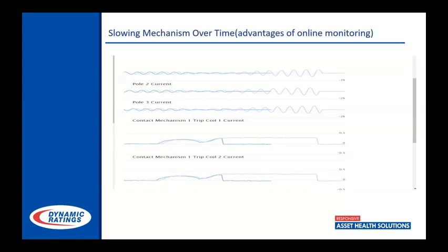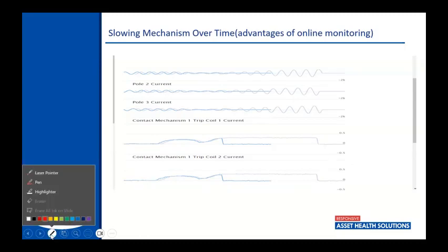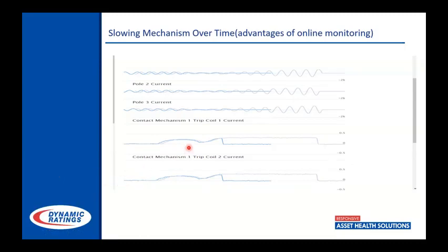So one of the things I really wanted to show with this is the advantages of having all of them. The aux contacts on this particular breaker, it was a switchgear type setup. Those aux contacts are operated off of another contactor in the breaker. So there's a pickup time with that. They were about 50 milliseconds behind the actual operation of the breaker. So we're really not getting a lot of data from the aux contact change of state for this one, which makes another good case that's really not where you want to time things.